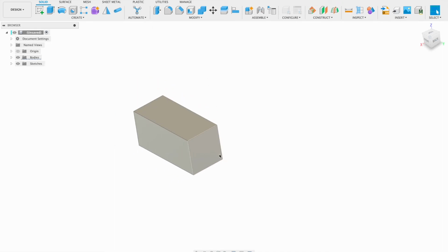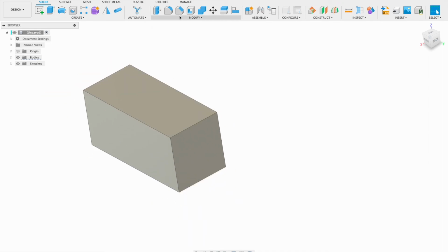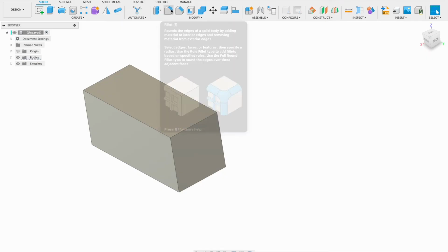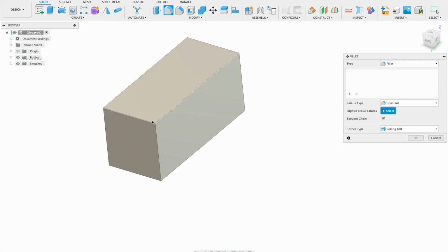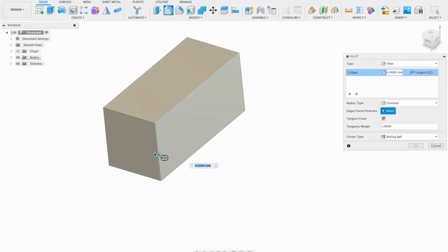else about the press and pull we're going to talk about after we talk about our next object, which is the fillet. Now, fillet is something that you will use a lot together with the chamfer. Now, the fillet, let's select these three edges, and with my arrow, I'll create a fillet.